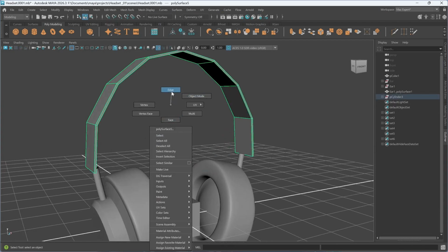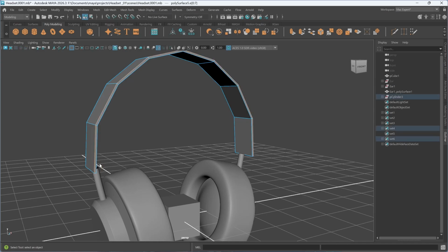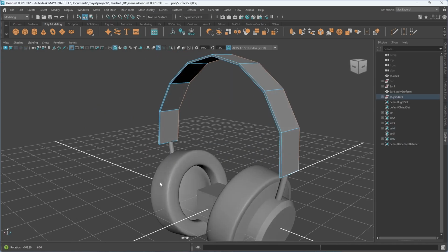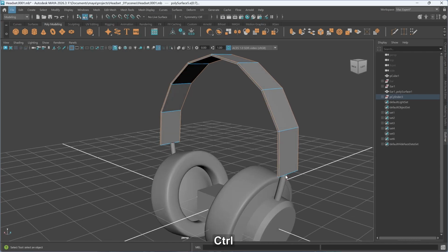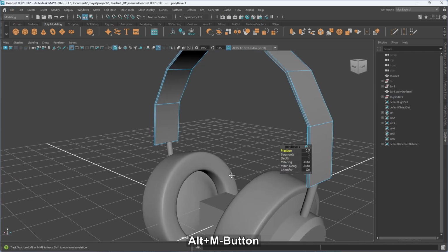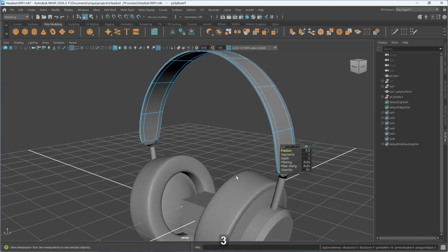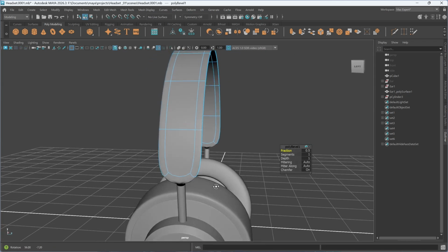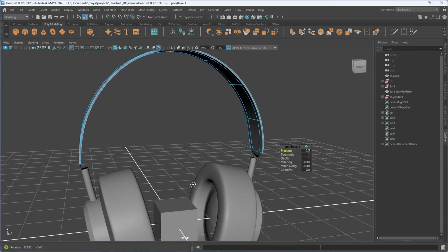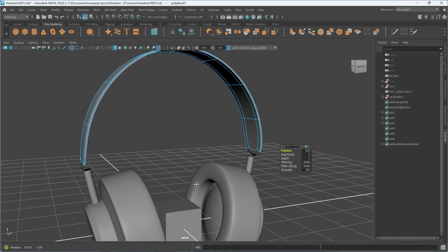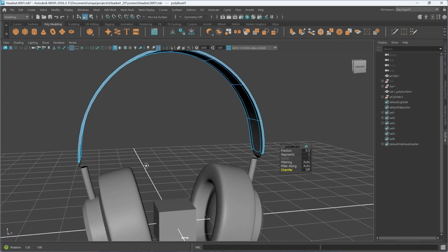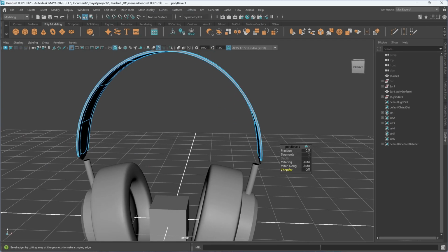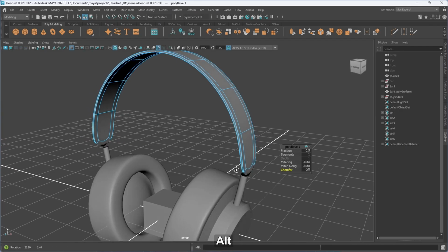Now we're going to select this loop round, hold on shift, select this, and also hold on shift, select hold of this loop, hit on Control B to bevel. Let's hit on 3 to go into the sub mode. Okay, those edges are okay. So maybe we can turn off chamfer. No, let's leave. Let's see. Yeah, we can turn on chamfer.